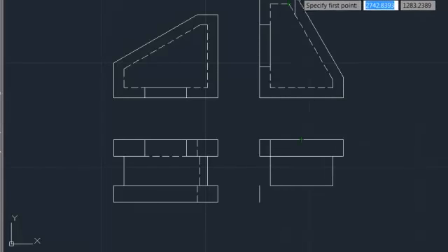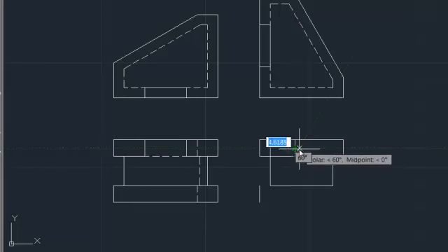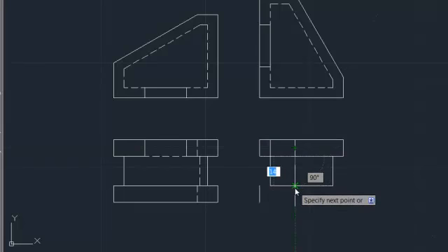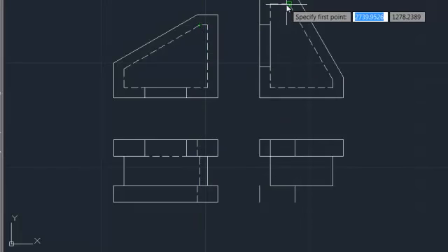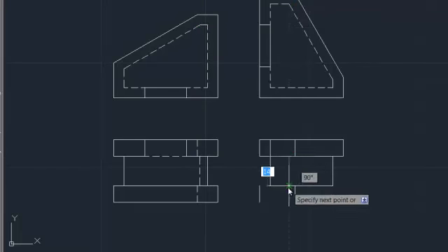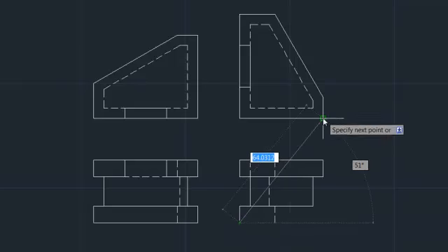Now, another problem: if you line up from these corners, you can see that that's the position of this outer line. You'll actually see that hidden line there, and similarly we'll see it down the bottom there, 8. This middle one though is not there. Same way we found the line over here before, we can find that this one is the corner to this line. And so this line, this line, this line, and that one are all hidden. And now it's just filling in the last little bits.